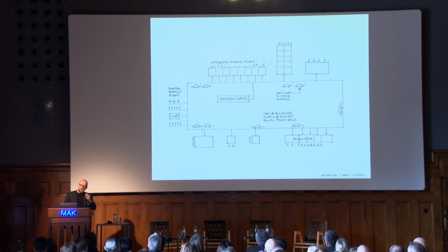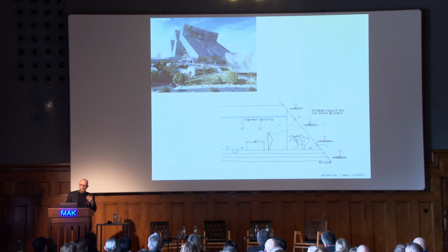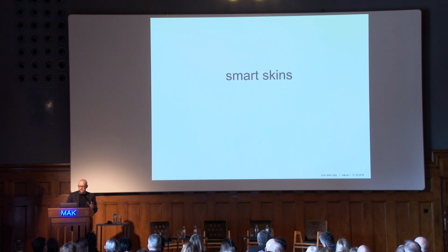So, introducing integrated systems and buildings which produce more than they need to use themselves. Here for Singapore, with Koh Phi Phi, this is the form of a skyscraper, so a vertical typology at the equator, so it gets very little sun on the facades. Therefore, the special form was developed to have these solar blades generate energy all year round, while at the same time not mutually shading each other, allowing daylight into the building to the occupants and allowing views, of course, out. So the forms develop from the specific challenges which we face at different locations, different tasks.